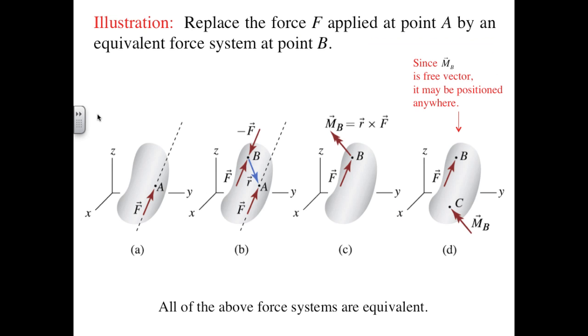Let's see if we can attach some intuition to that compensating moment term in the resultant moment by considering the case of a body subjected to a single force F at A, as shown in figure A. For reference, I'll put a dot in the middle of the object to indicate its center. We'll call that G. From our perspective, the force F is to the right of the center, and the right-hand rule would tell us that this force would tend to impart a rotation coming out towards us, for instance, like this.